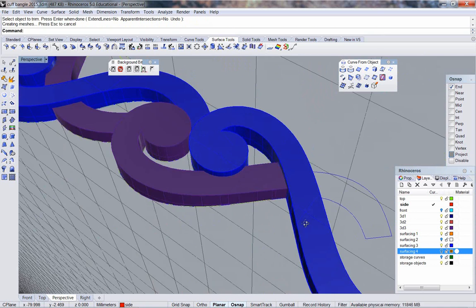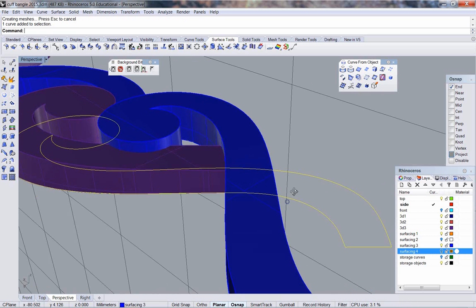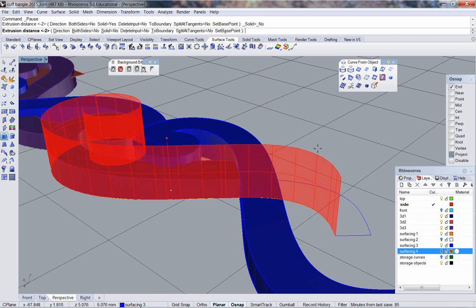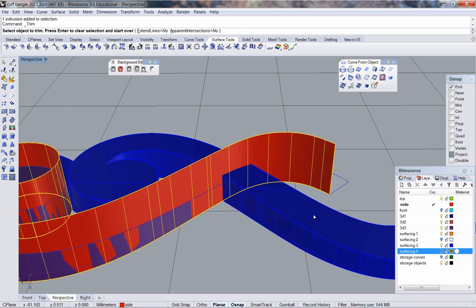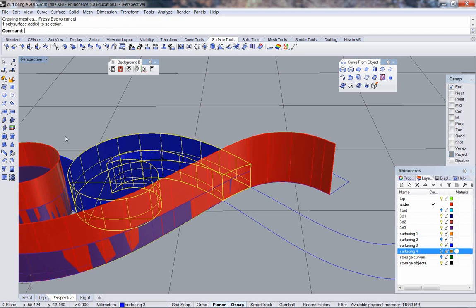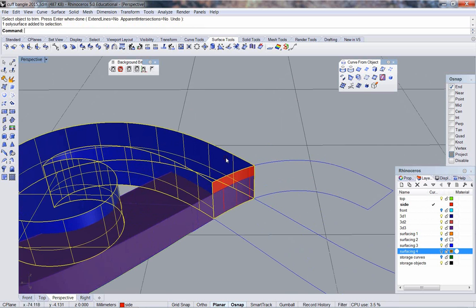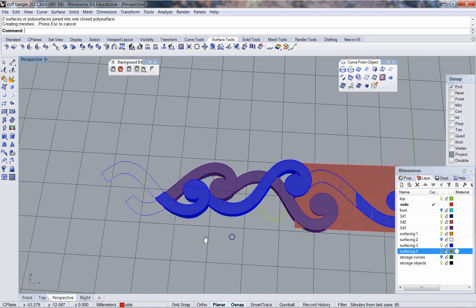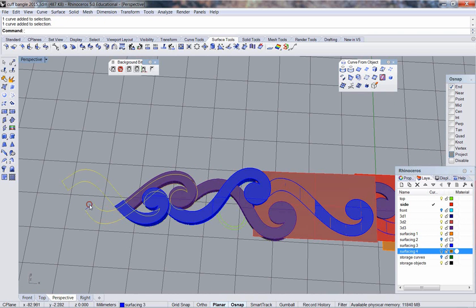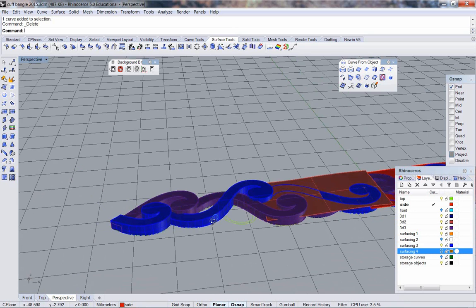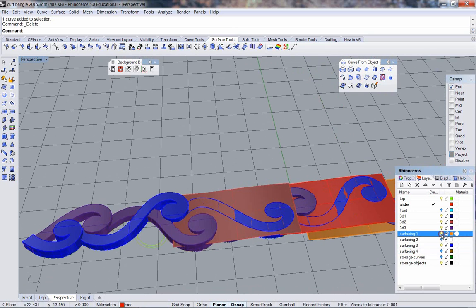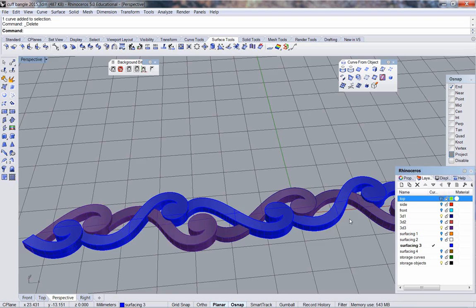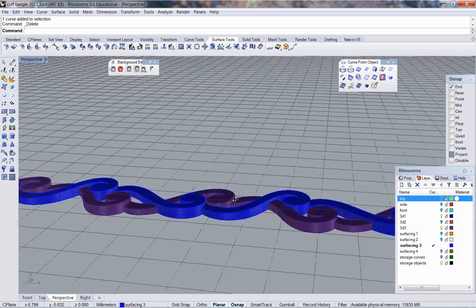I would cut off the end of that there. Borrow this curve. Extrude that straight up. Trim this off here. Borrow this to close off the end, so it at least looks decent. And now I've discovered where one of the trickiest parts of my model is going to be. One of the trickiest regions of my model is going to be right in there. Okay. That's one of the goodnesses of this step of the modeling process, is to find out where your challenges lie. Okay. So that's the basic maquette for my bracelet.